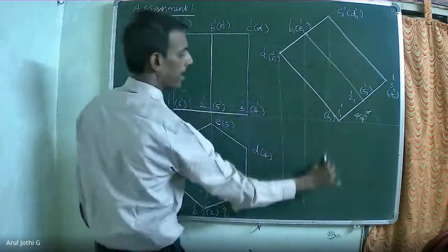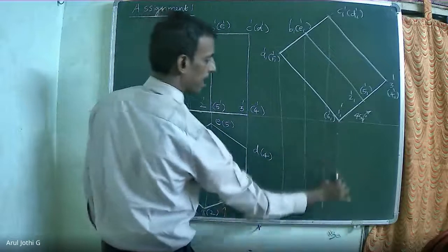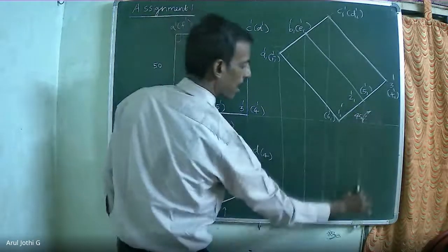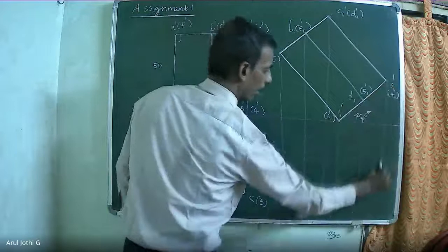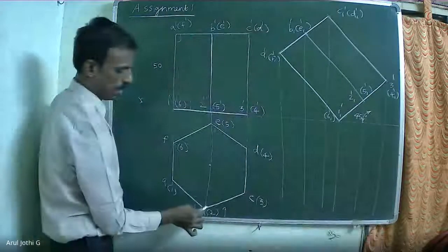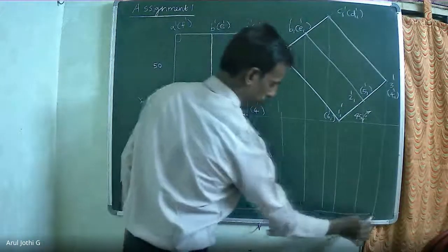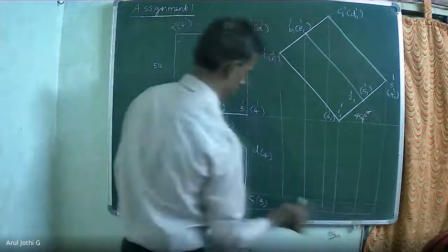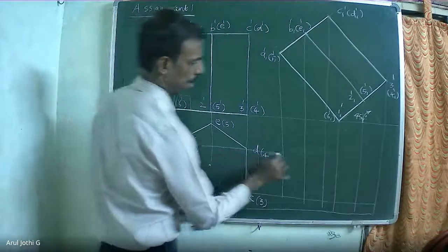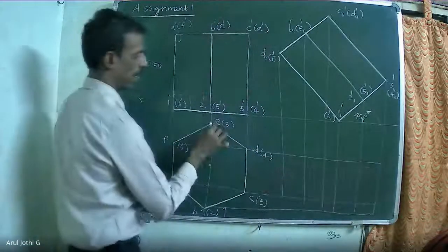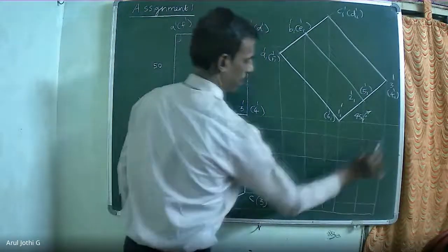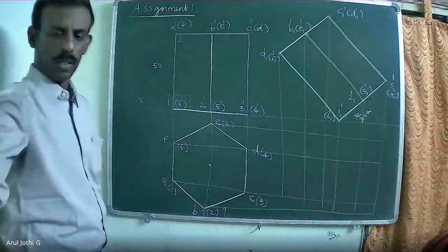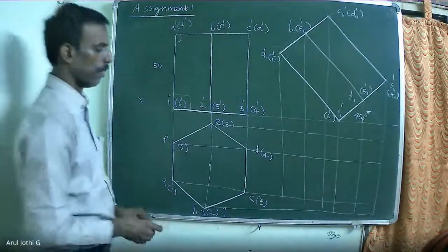The corresponding corner points will be intersecting. Extend all the corner points of the top view horizontally. How to mark the corner intersection points in the top view?